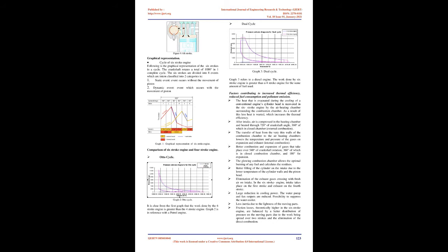Reduction of exhaust emissions due to less fuel being consumed and the real prospect of meeting Euro 4 emissions standards, doing away with the catalytic converter. Possible one-piece engine block and head casting, saving more manufacturing costs. Usable torque at as low as idle means suitability for lower RPM operation and adaptation to CVT, constantly variable transmission.